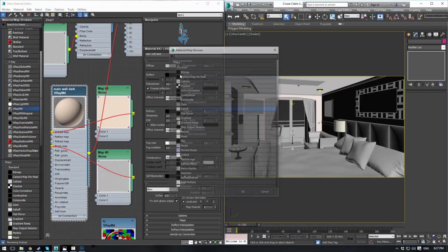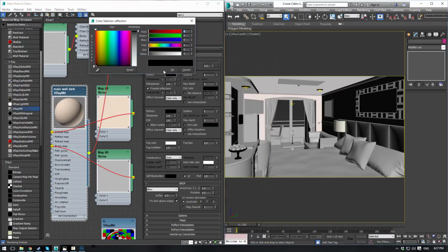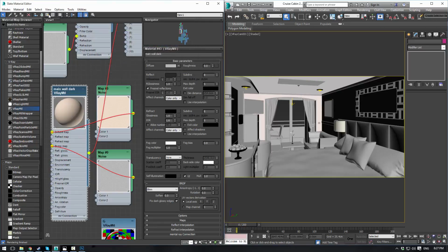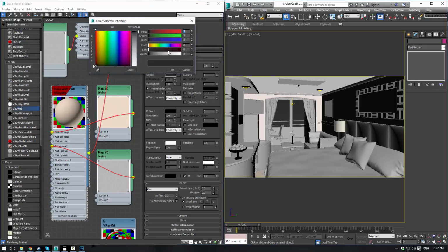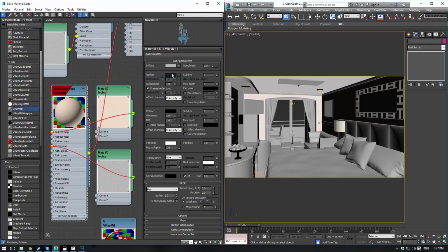And let's actually, in the reflection slot here, give it a very low value, like a 5 in the reflections there. If you give it more, you'll see you have a lot of reflection coming in there. We need very, very little, maybe even a 3 will work. And then give it a glossiness of 0.9, 0.5, 0.6, 0.7, 0.8, 0.7. 0.7 should be good.